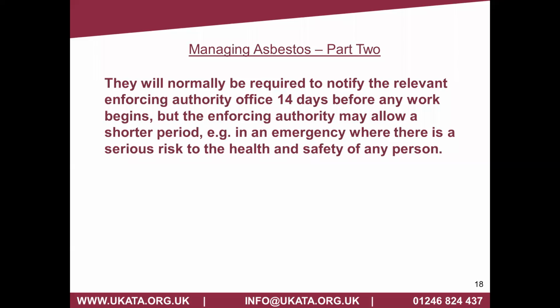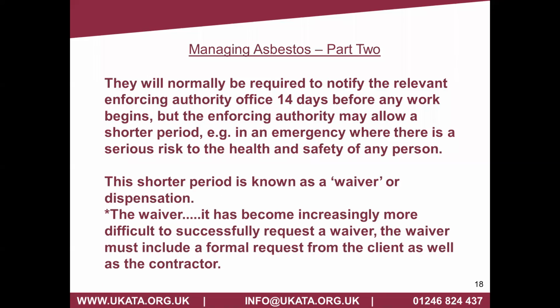Now, on occasions, we can't wait 14 days. It may be that there's been some weather and it's damaged some asbestos, which is completely out of our control. There may be some malicious damage to areas where there is a potential health and safety risk to other people. So in some cases, a waiver could be requested. This is a shorter period, also a dispensation of the 14 days. And of course, the idea and principle behind that is that where there is a serious risk to health and safety, and of course it wasn't foreseeable, then of course the contractor can request a waiver.